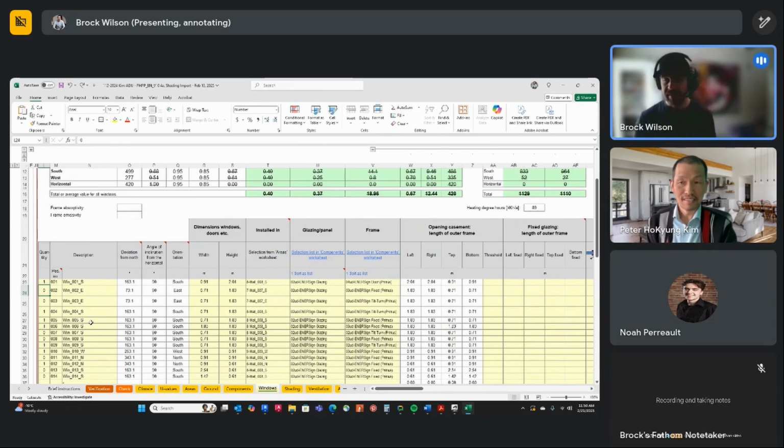I would love to keep the south windows, but perhaps we optimize them in terms of what type of coatings they have, in terms of the solar heat gain coefficient. So we play around with those particulars so that we can try to keep them or optimize them in terms of the size.